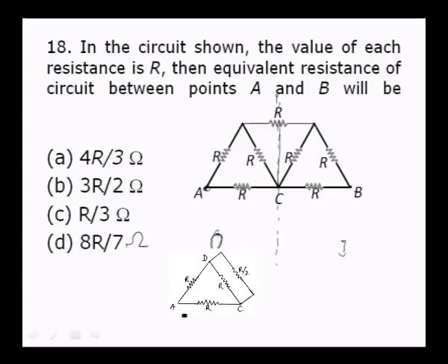This is the resistor. This is A and this is C and this is the resistor R. I will give the points A, B, C, this is D and this is E. Okay, this is the resistor, this circle is over R. See here, the resistance will divide equally, that is becoming R by 2, R by 2. Now, the resistances between D and C are in parallel. R and R by 2 are in parallel.